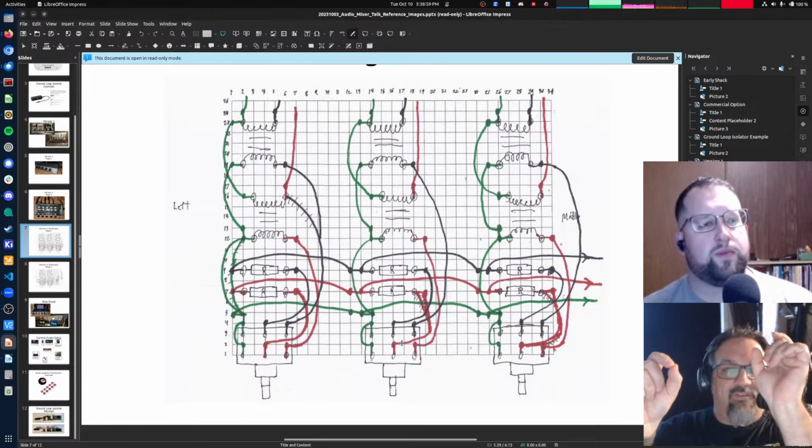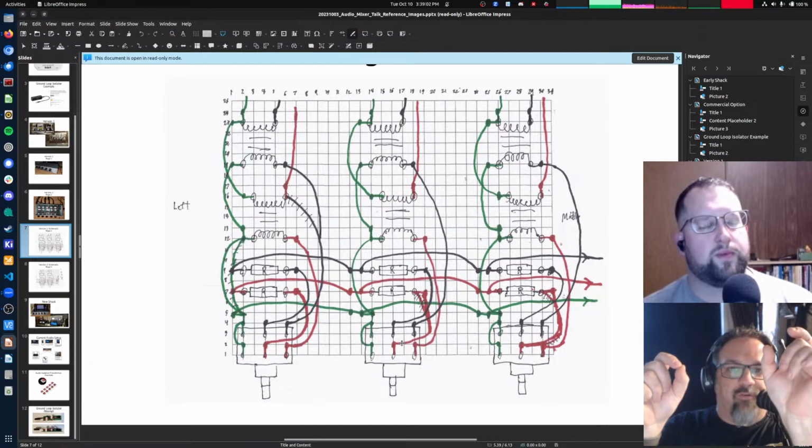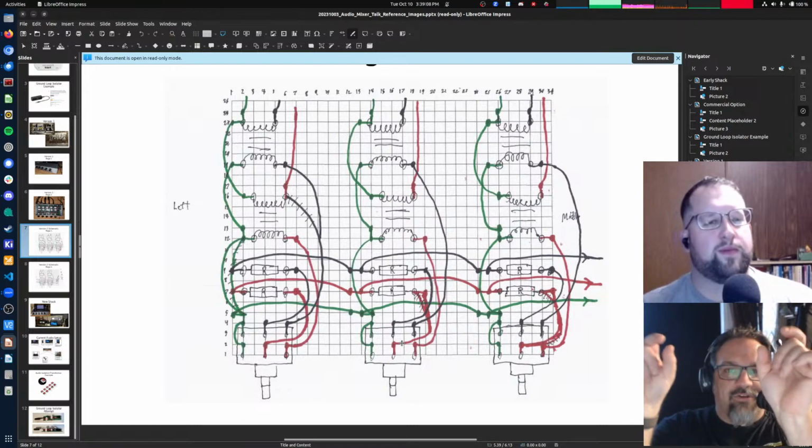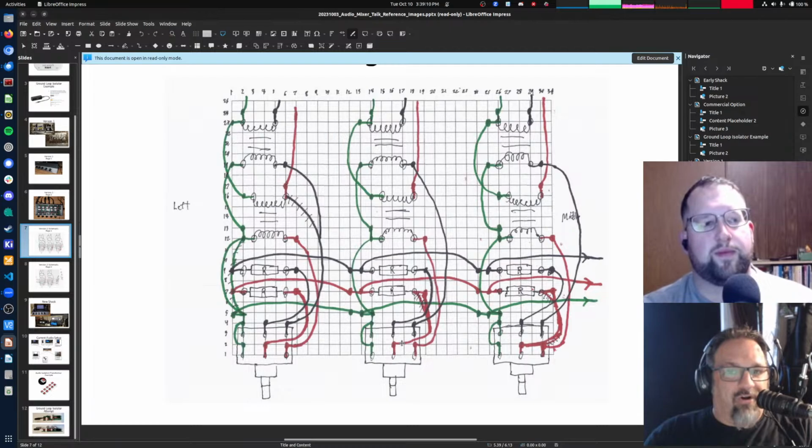And if you drive the speaker output from one radio through a 2K resistor to the speaker output of the other radio, those speaker outputs are usually in the order of like 4 or 8 ohms, which is a much lower impedance, and that will absolutely dominate the circuit.